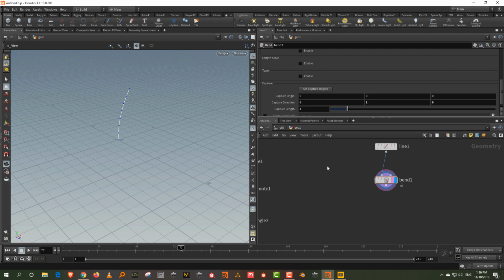Okay. And then there are two ways to do this. I'll tell you the simpler way. Okay, so we did the PT num divided by num PT, fairly early on. That is one way to do it, which is to generate a ramp going from 0 to 1 based on the curve direction. But there is another way to generate an automatic attribute which will do the same thing for you.